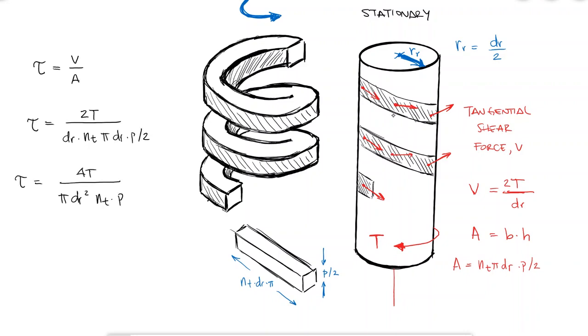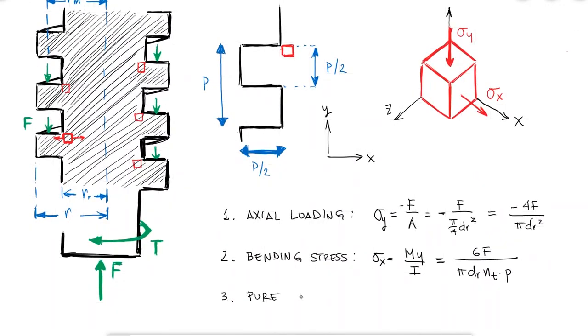And since it's a shear stress affecting the faces of the stress element that are normal to x and pointing in the z direction, we call these tau xz or zx, since there needs to be a reaction on the adjacent face. The expression would in fact have a positive value for left-hand screws like the one in this example, and negative for regular right-hand screws, but you will see that the sign doesn't make a difference for what we are trying to figure out at the end.